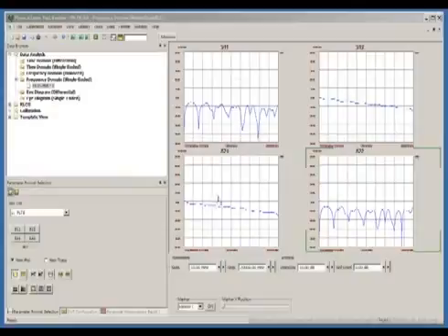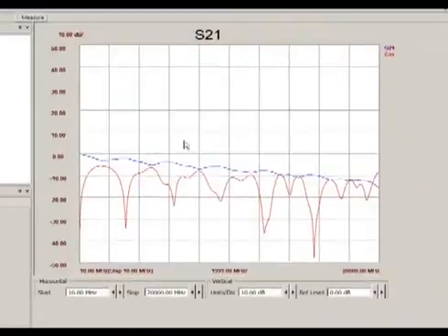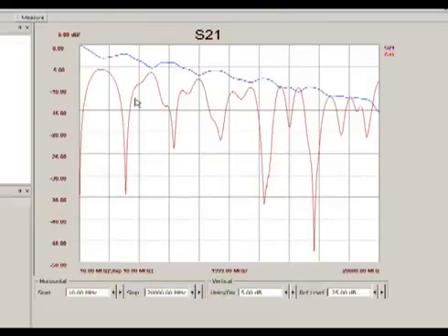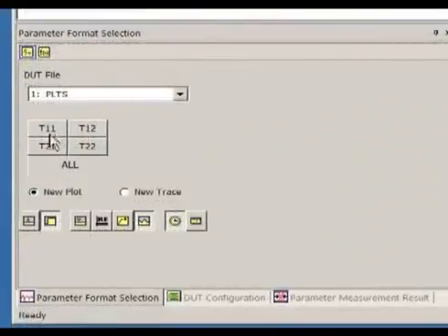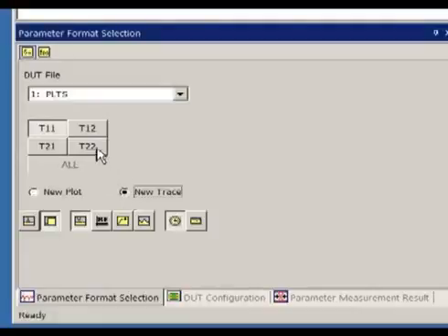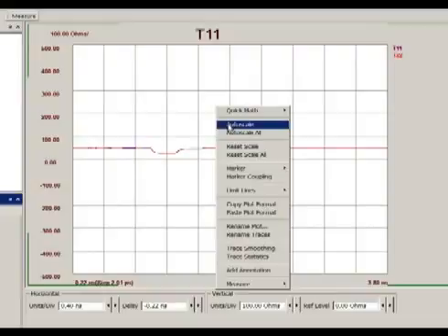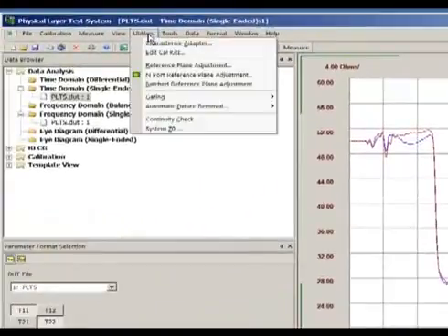to take the measurement. Selecting the frequency domain S21 and S11 measurements of the dot and then right-clicking on the graph to auto-scale the data provides a clear view of the quarter wavelength resonances caused by the length of the 25 ohm impedance discontinuity. In the time domain analysis of the data, the impedance reflection data for port 1 and port 2 are selected, and then the data auto-scaled for checking the symmetry of the probe to PCB connections for fixture removal and verifying the expected 25 ohms dot impedance discontinuity.